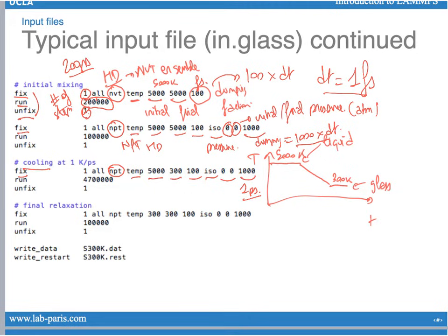So here, when you open the fix, you define a new fix, which defines the new constraints that you want for your simulation. You want the simulation to be in NVT, you want the temperature to be 5000, and those constraints are going to be applied until you unfix them. So here you put the name of those constraints. Those constraints are going to be applied until you unfix the constraints that you have called number 1.